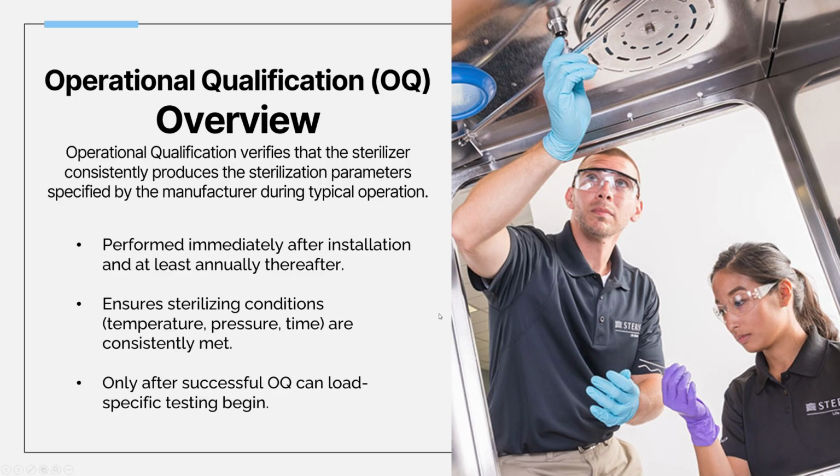And moving on, we have operational qualification. So OQ confirms the sterilizer can meet the conditions needed to sterilize, for example, 132 degrees Celsius for 4 minutes. It's done after installation, then annually or after major services or repairs. It includes measuring heat up times, verifying sensor readings, and comparing results to manufacturer tolerances. OQ must be successful before performance qualification begins.